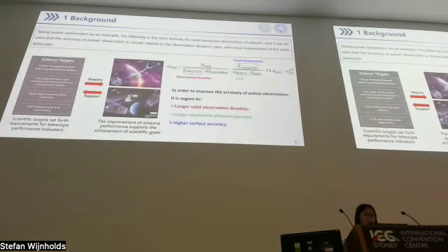About structural response, data collection and statistical analysis of sensors arranged on the reflective surface are carried out. The wind effect of the antenna is obtained by means of pressure measurement, force measurement, and speed measurement. The wind coefficient and the wind pressure distribution of the reflective surface at different azimuth positions are simulated.